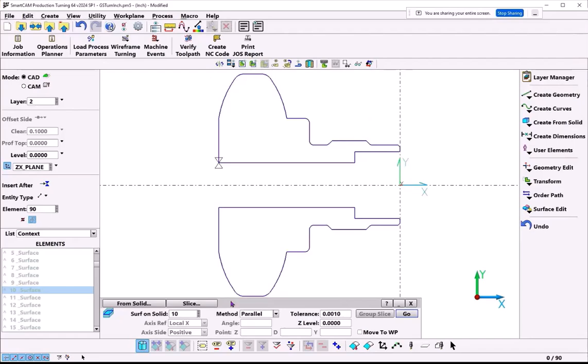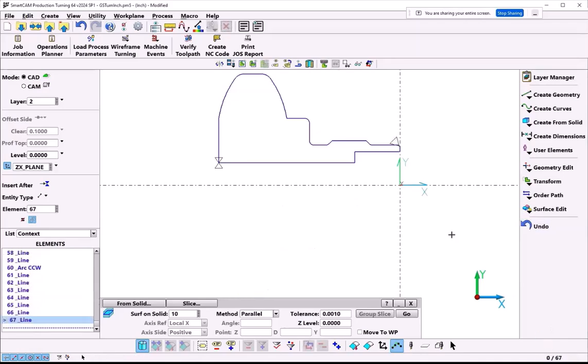The thing is spinning. So why don't we go ahead and delete this bottom profile. How we can do that is on our group toolbar, we have our group arrow, and we have a bunch of other things that we can use. But there's one that's called Add Elements in a Profile. I call it the profile picker. It's turned on just like a group arrow would be. Then we can pick any element in this bottom profile, and it puts the entire thing in the active group. So I've got 23 of 90 elements in the active group, looking at the bottom right. Okay, now if you hit your delete key, that bottom profile goes away.